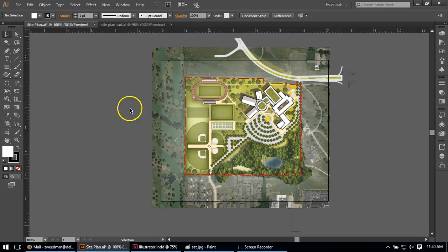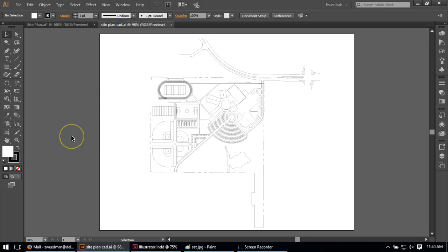What I've already done, and I've already presumably designed this and drew it in AutoCAD or Revit or wherever other software you're being an architect in. And I've already brought that work into Illustrator here, and I have other videos explaining this in detail, but what I do most of the time is I print a PDF for Illustrator, and there's several reasons for that. One is better line weight control, better scale control, and most importantly to have better editing control later on in the future. And so I know there's other ways of doing it, but I highly recommend that, and you can go to other videos if you want to see that. But essentially I just went to AutoCAD in this case, but just went to File, the Print Plot dialog box, set up a PDF printer, set up the size and the scale and everything else, and sort of printed it. And so here we go. Here's the CAD stuff as it comes through.